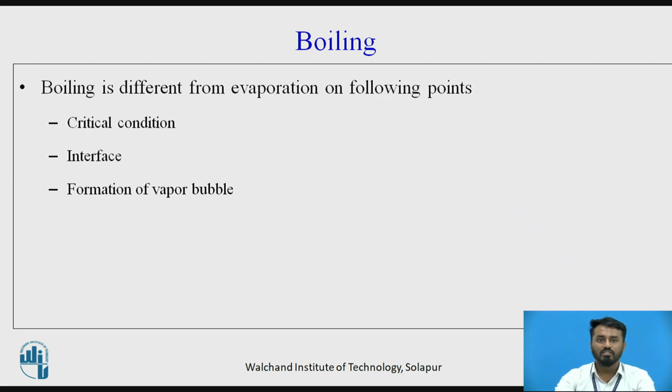So we are going to discuss the difference between boiling and evaporation. In the case of boiling, the temperature at the interface should be greater than or equal to the saturation temperature at that particular pressure, and evaporation takes place at normal conditions.